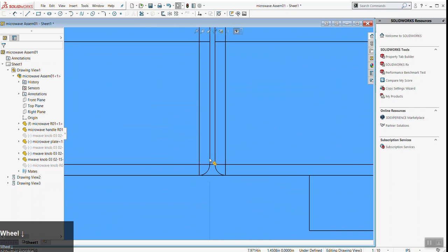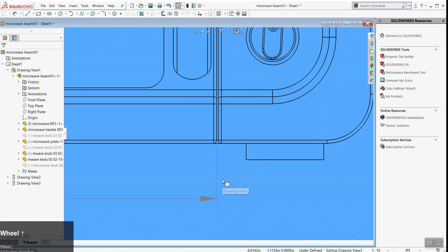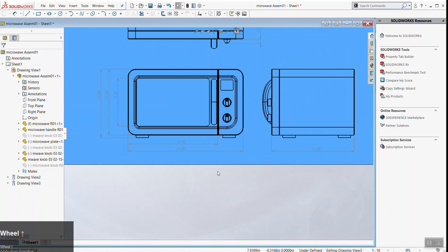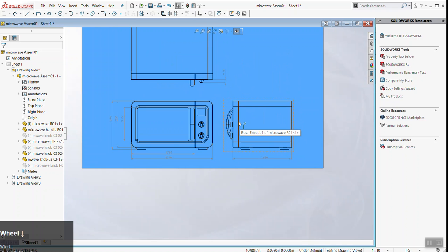So here with the door, depending on how the door is mounted and such, it may be 0.05 inches to the right. At what point does that door start hitting that edge? That's how they determine the tolerance so that the door still functions. We're getting in the weeds now, but it's a long way to say that's why we do these drawings. That's one reason for them, a sort of contract of what's acceptable and what's not acceptable. Any questions on any of that?